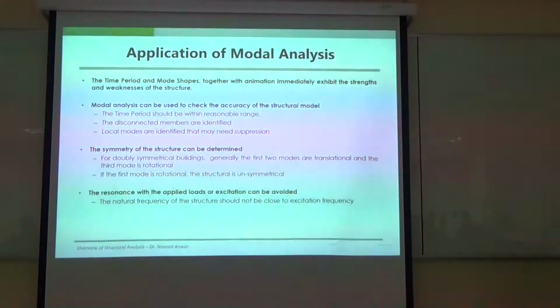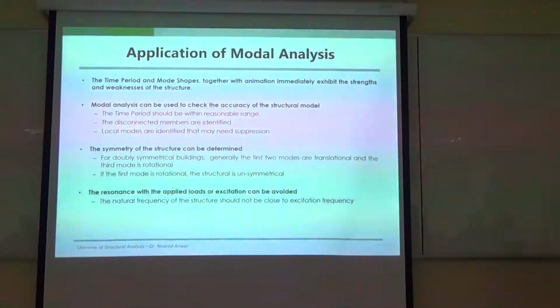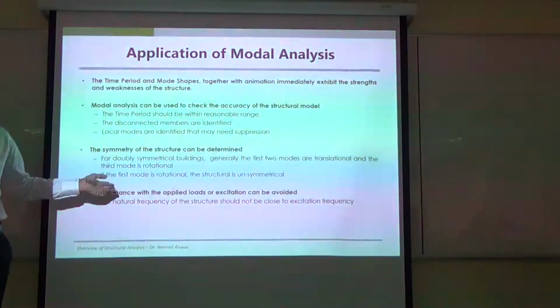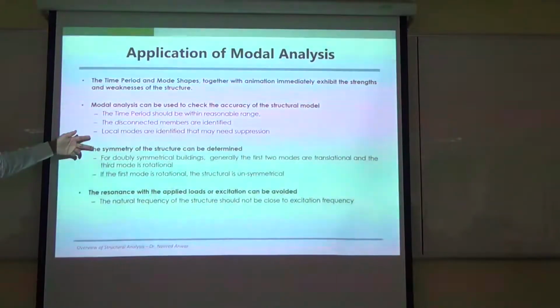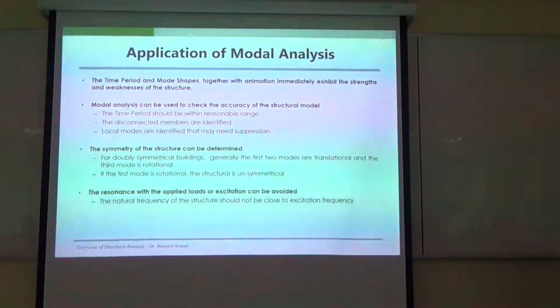And resonance will increase the force by 10 times. So their weight, whatever their weight is, will become 10 times more than their actual weight because of the resonance. So they are advised to break the step so everybody does not step the same way. So resonance, dancing, floors, and some stuff like that, you have problem there. And so many things can be checked from the model analysis.